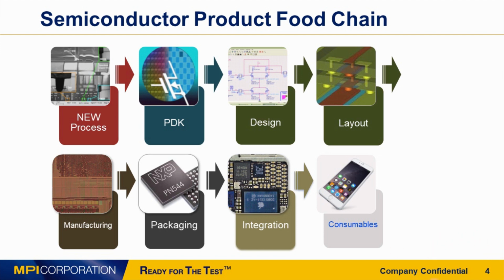Development cycle of the new semiconductor consumable product consists of multiple steps. At first, the modeling test chip is fabricated on the next generation semiconductor process. This chip includes all possible device types, geometries, and configurations. All these devices must be characterized at all possible operation conditions. And all these need to be done multiple times. Process development and modeling engineers request tons of data to be captured to include statistical deviations of these process parameters into the device model.